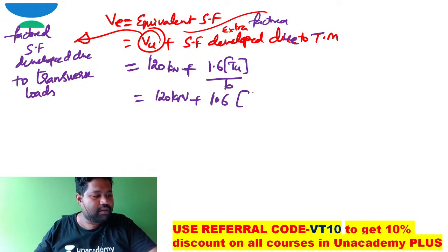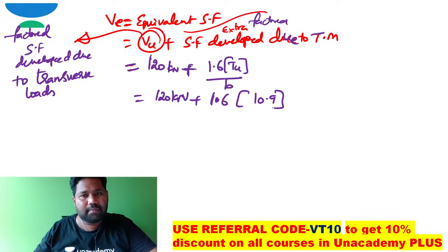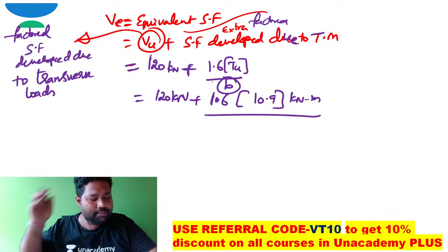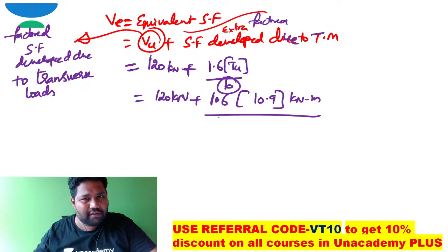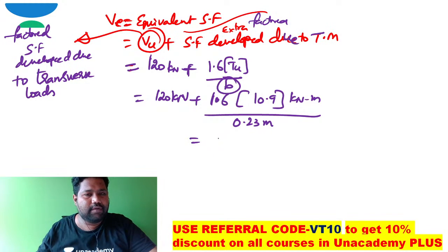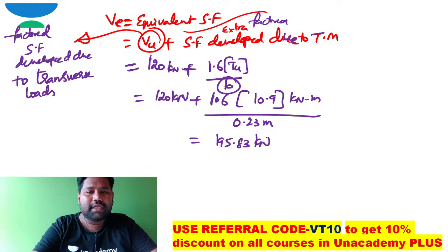The factored torsional moment is, I think, 10.9 kilonewton meter. So the width of the beam should also be in meter. Width of the beam is 230 millimeter, which in meter is 0.23 meter. If you cancel out meter and meter, you are going to get the equivalent shear force. The equivalent shear force is 195.83 kilonewton. Right?